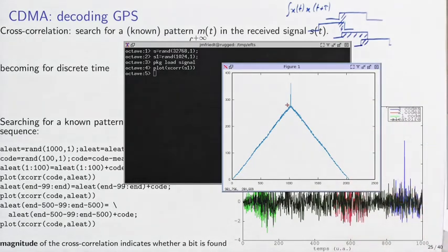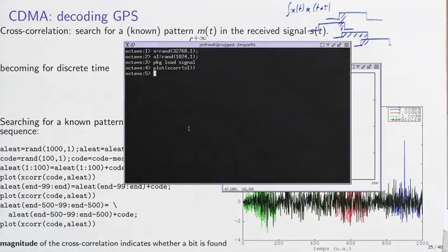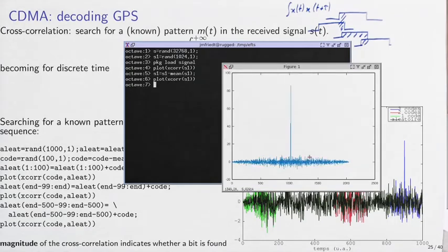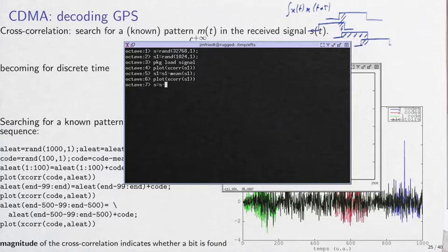So what we see here is that this triangular shape is actually the overlap of the reference signal with the measurement signal, and needs to be cancelled out. How do we cancel it? Otherwise, this correlation peak might be here on the side, and if I just search for the maximum, I might be confused by this local maximum. So how do I make sure that I do not have this background shape? I always make sure to remove the mean value of whatever pattern I'm correlating. And if I remove the mean value, now I have a flat background and only a unique correlation peak. So same story for S. We always remove the mean value from whatever quantity we wish to correlate.